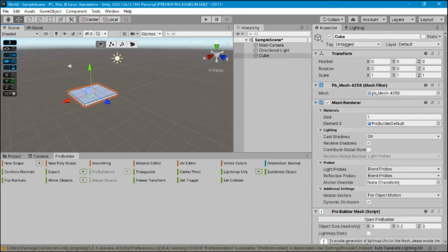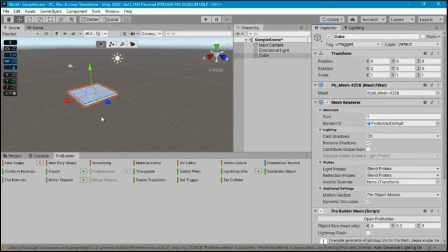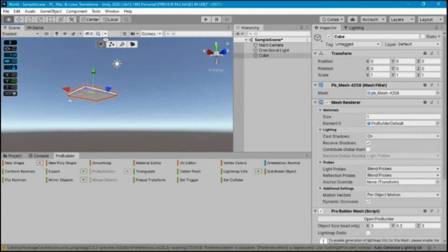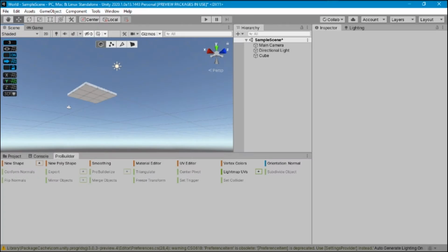In order for this system to work, all objects must have their pivot point at the bottom center. Which means we need to select the bottom face and then set the pivot at the center of that face. To do so, first, we need to make that face visible. Please press the Alt key and notice the mouse pointer becomes an eye. Drag the mouse up while holding the Alt key. The camera will move down while keeping the object centered. Keep dragging until you can comfortably see the bottom face.